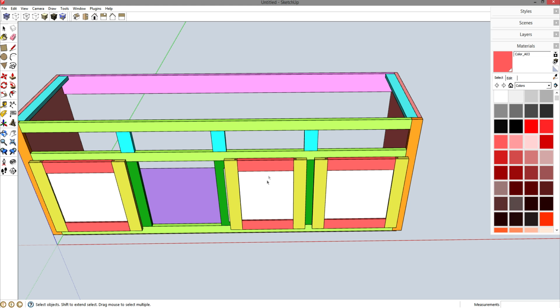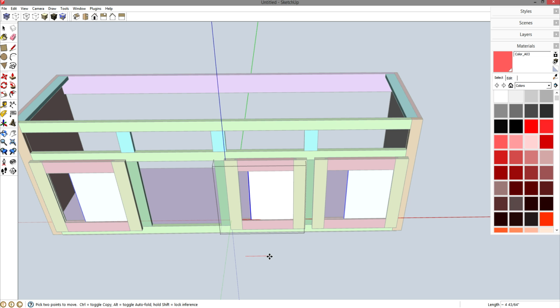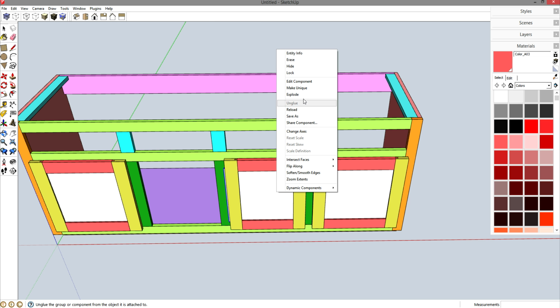That 2 1/4, I got to do the same thing to this panel. So let's double click to edit the part, use a window to select the left hand side, M for move, and we're just moving just the small geometry, and it is a copy still. So let me back up. Right click and say make unique.